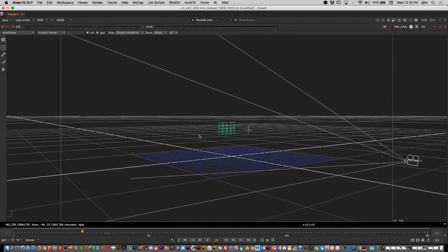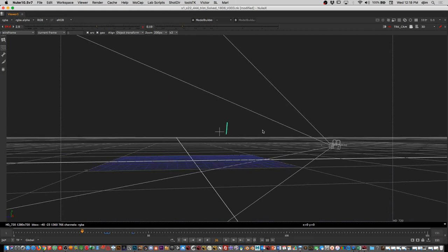So I'm going to go back like that and see if it's actually slanted forward. If it's slanted forward, I know we're too far, right? That means I didn't ever get it perfect. So at this stage, you could actually go in, and if you notice it's slanted when it should be straight, you could look at your point cloud data, or you could go to the edit mode. And in the edit mode, you could go in, right click on top of the object, and you can select the faces or the object itself to be able to manipulate it.